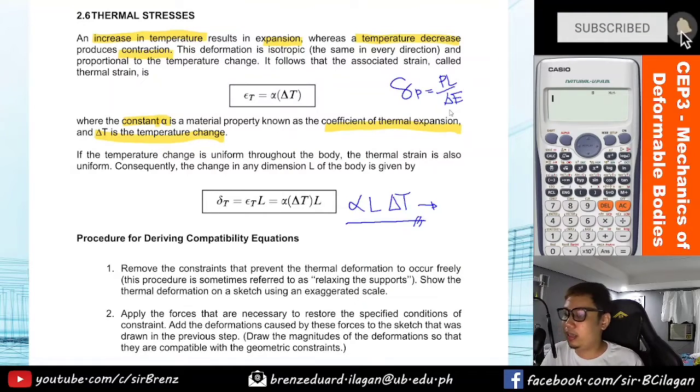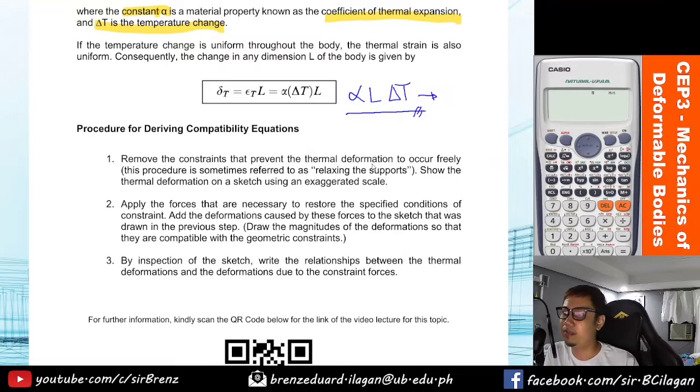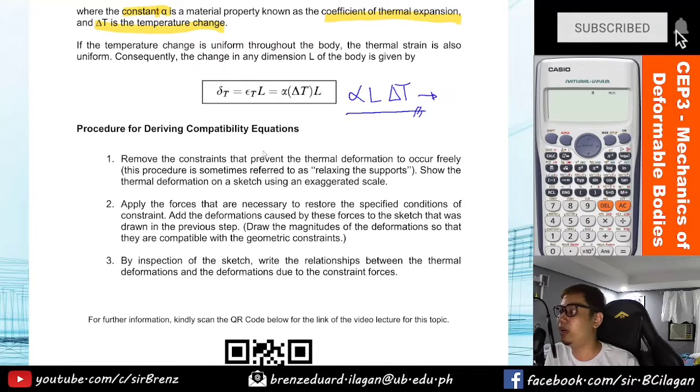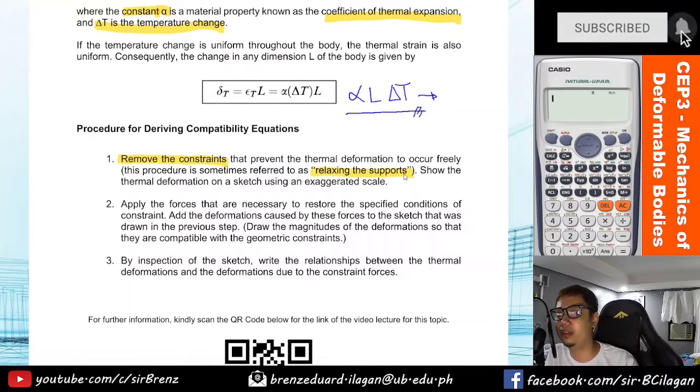Okay, so next, what is the procedure in deriving the compatibility equations? Ito yung mga gagawin. Step-by-step procedure in solving a problem considering a thermal deformation. Step number 1: remove the constraint that prevents the thermal deformation from occurring freely. This procedure is sometimes referred to as relaxing the support. I-relax mo yung support. Kung fix yan, tanggalin mo yung isang fix.